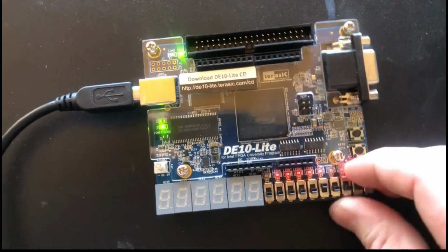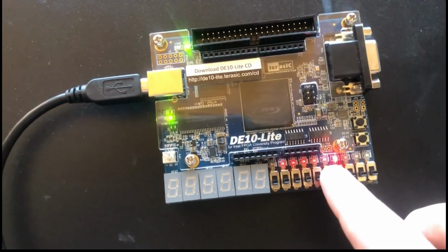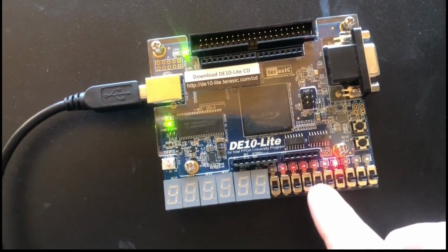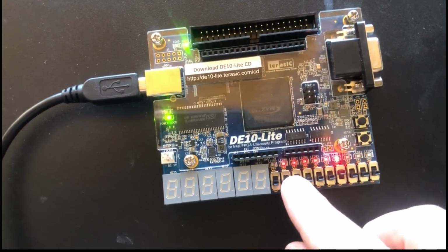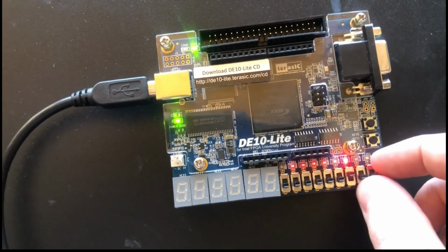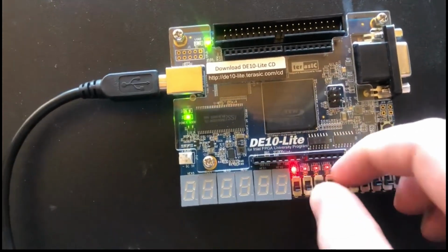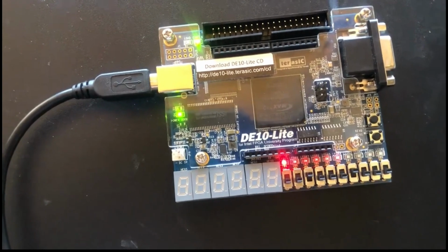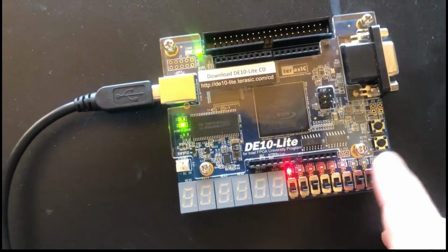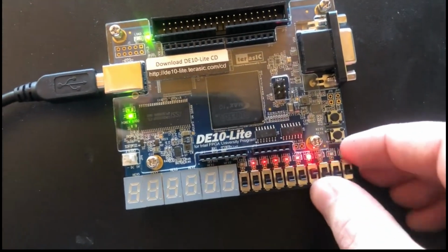But what happens, let me actually just flip these all low. I'll flip 8 on this one. We'll see 8 goes high. And if we exceed 15, actually, no, it is exceeding. If we were to add that together, we'll see that carry out now goes high because the max it can support is 15.